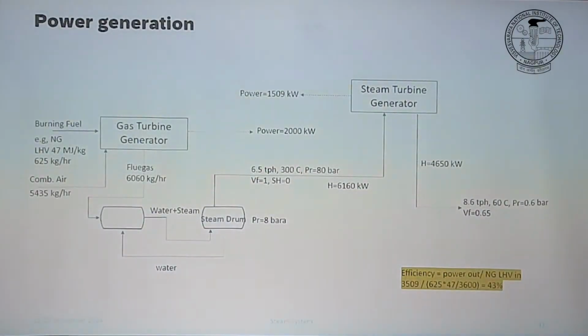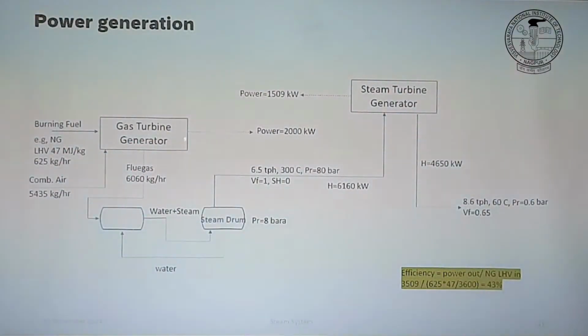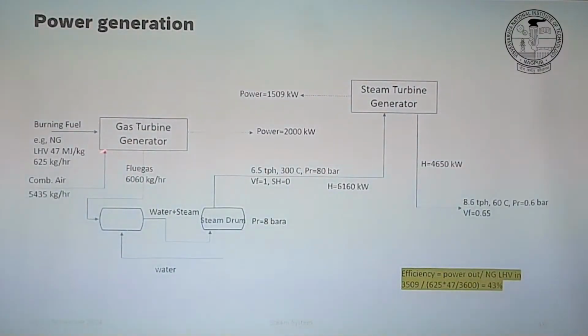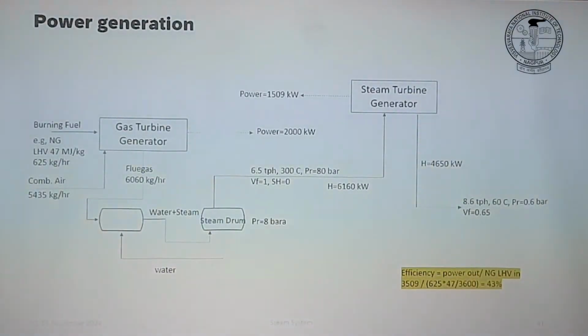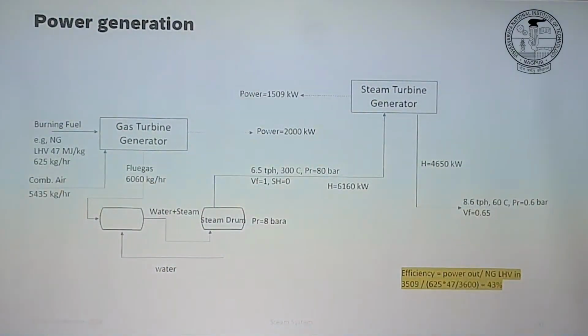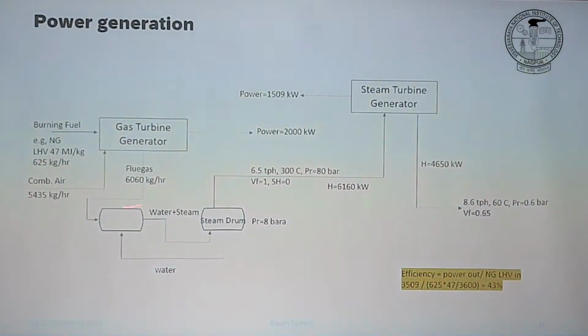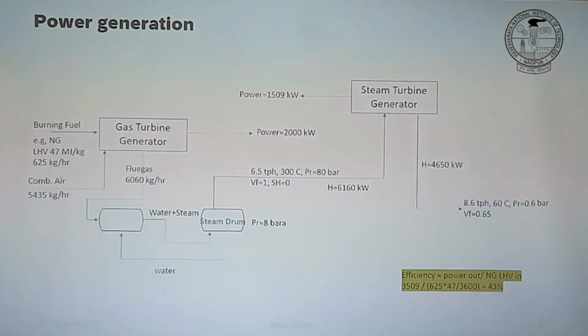Okay. How can we further increase the efficiency? By having two cycles. First, from the flue gas we already generate power directly. So earlier what we saw, we burn fuel, and from the hot flue gas we generate steam, and this steam we use to turn the turbines, right? But what else can we do? We can directly turn the turbine using the flue gases, if these flue gases are at high pressure.